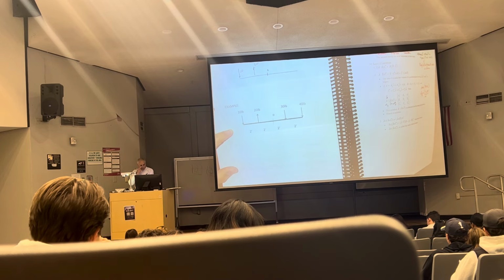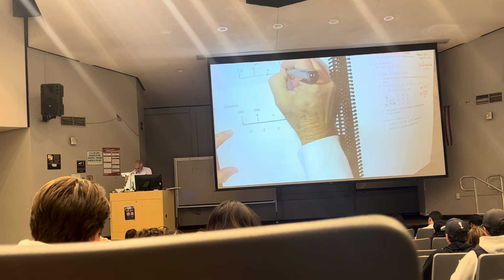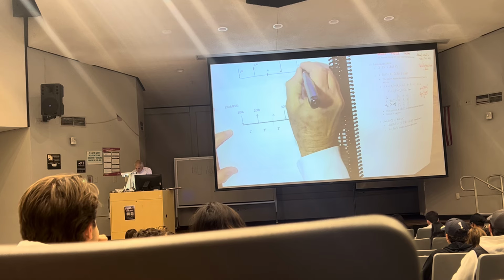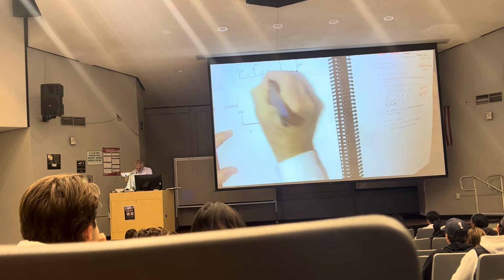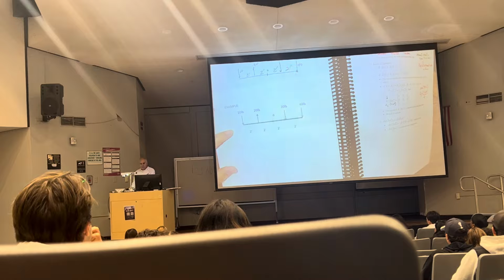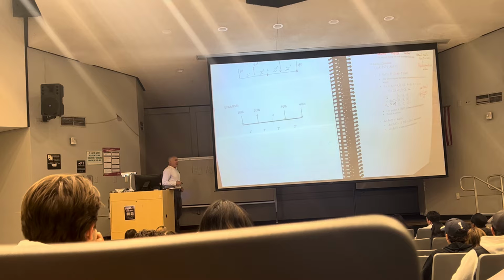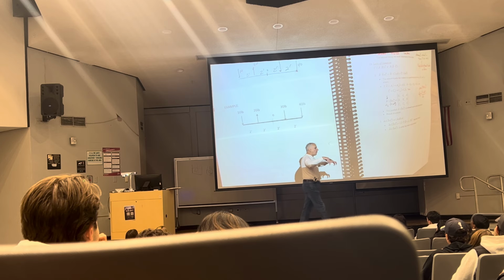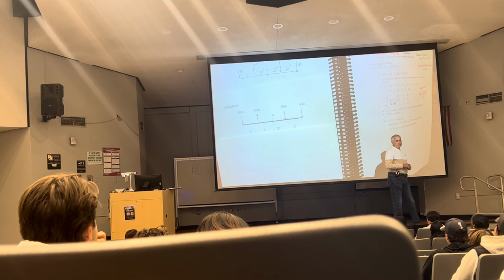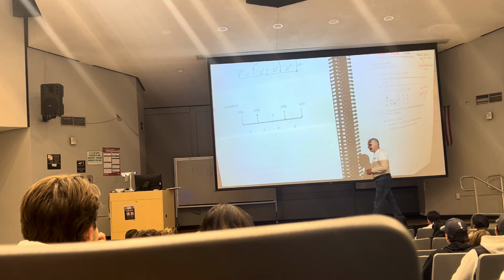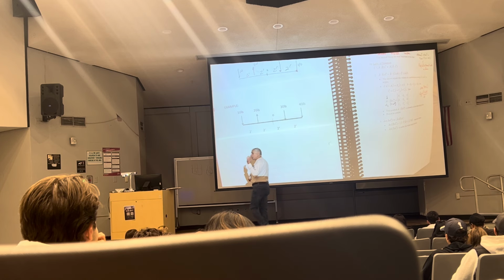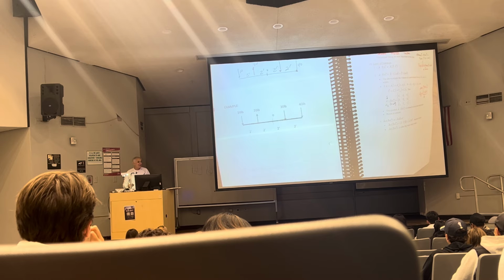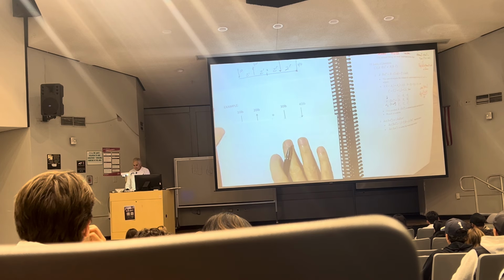Here's my moment center. 30 pounds, 40 pounds. There's 2 feet in between. I'm going to find what is the moment being generated by these 4 forces at O. And I'm going to do it 2 ways. I'm going to sum moments clockwise, and I'm going to sum moments counterclockwise. You're going to see it comes out to the same thing.